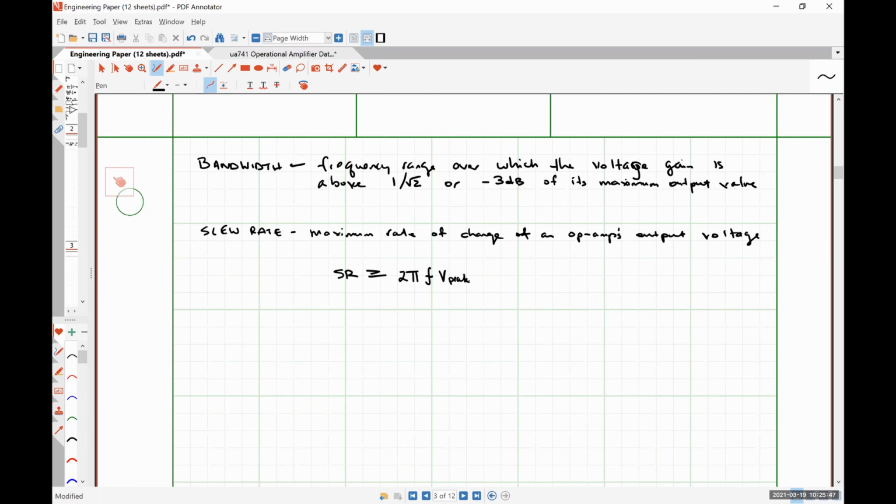Meaning, if I had lowered our amplitude, let's circle back here, right? I have a triangular wave. If I change this from having an amplitude of 1 to an amplitude of 0.5 peak value, and rerun it, there's not as much distortion as we observed, because the slew rate distortion depends on both the frequency and the amplitude of the sinusoid. Okay, that's what I was trying to get at.